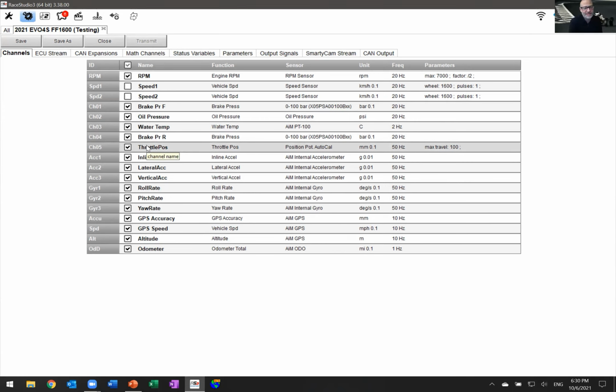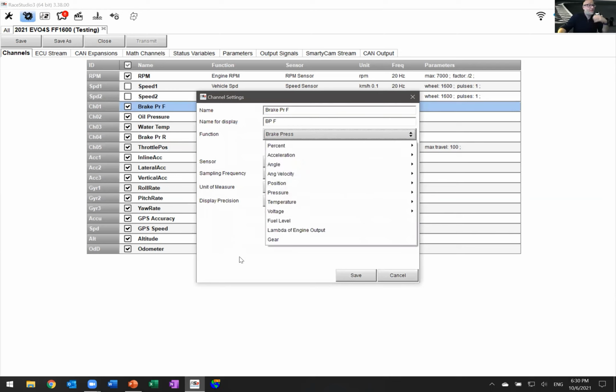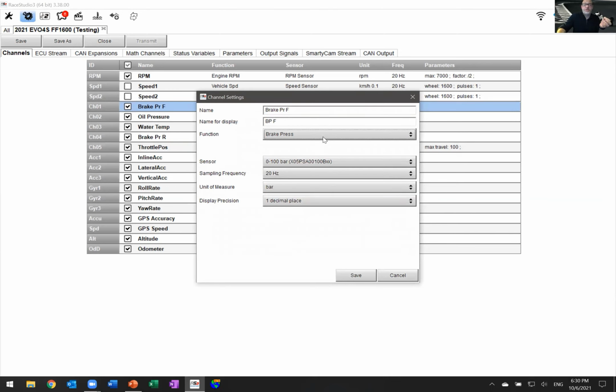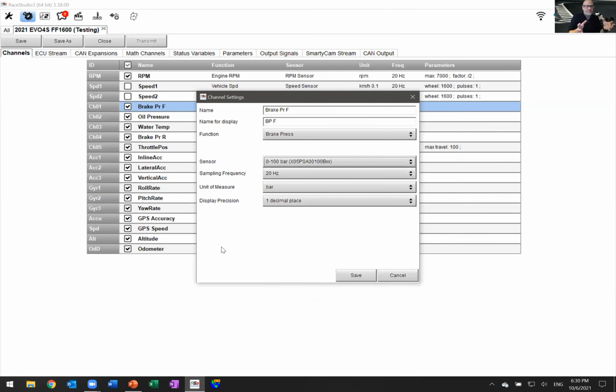Now, if you're ever wondering how to set these up, and we might do a webinar on those, effectively what you do is you plug it into the device, you double click on the actual channel itself. You can name it whatever you want. I've named it brake PRF, because you can't have an extremely long channel name, so I was just fitting it in. You tell it what function you've got. You've got all these functions as to what the sensor will be, and you'll get these when you buy your sensors. You'll say what actual sensor it is, and it's a long list of available sensors, which you'll have when you actually get it, and it'll have a serial number and a part number with it.